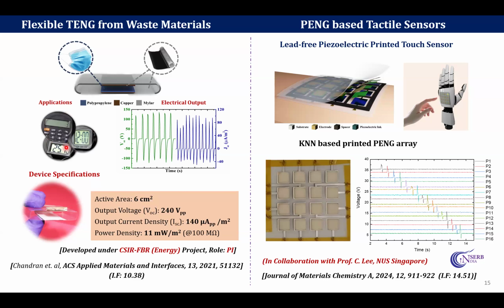Almost at the same time, our industry is into lead-free piezoelectric nanogenerators also. So we developed various lead-free, printable piezoelectric nanogenerators based on sodium potassium niobate ink. You can see a 4x4 array of sensors which we have printed on a flexible substrate.